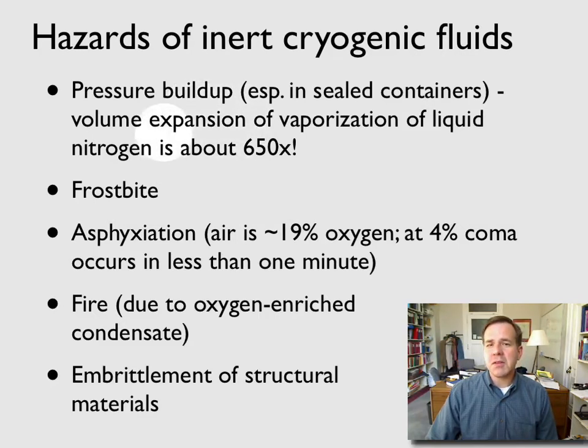In this regard, it's worthwhile to note that when a liquid vaporizes, there's a huge volume expansion associated with that. It's a factor of about 650 times for liquid nitrogen going to gaseous nitrogen. And obviously, if that's in a sealed container, that can lead to a huge buildup of pressure and therefore explosion of that container. So we never want to seal containers completely that have cryogenic fluids in them. We always want to make sure that there's a way for that pressure to be released.